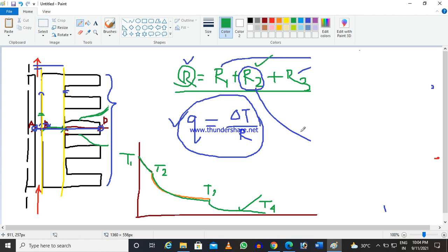So we can consider that constant irrespective of temperature. So from this delta T and R2 you can estimate, by applying the formula natural log R2 by R1 divided by 2 pi KL, this Q.